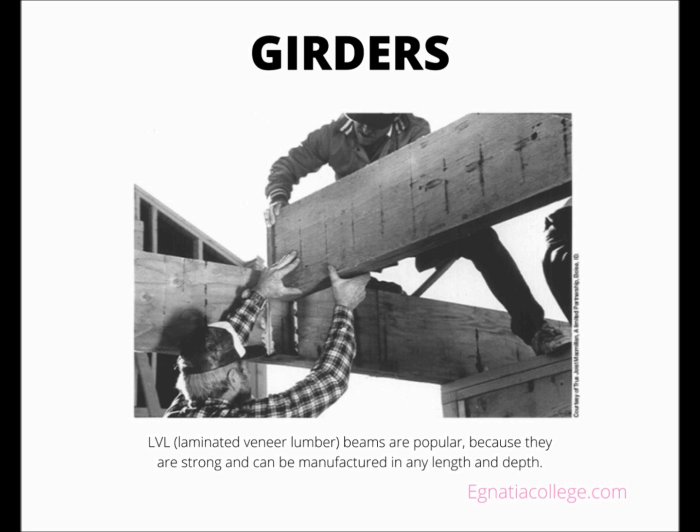Girders. Before the total length of the columns or height of the piers can be calculated, it is necessary to determine the size of the girder and its relationship to the floor joist. Three types of girders are commonly used in residential construction. Steel beams are often used where strength is a critical factor. Built-up wood girders are constructed on the site. These consist of 3 or more pieces of 2-inch lumber nailed together with staggered joints to form larger beams.